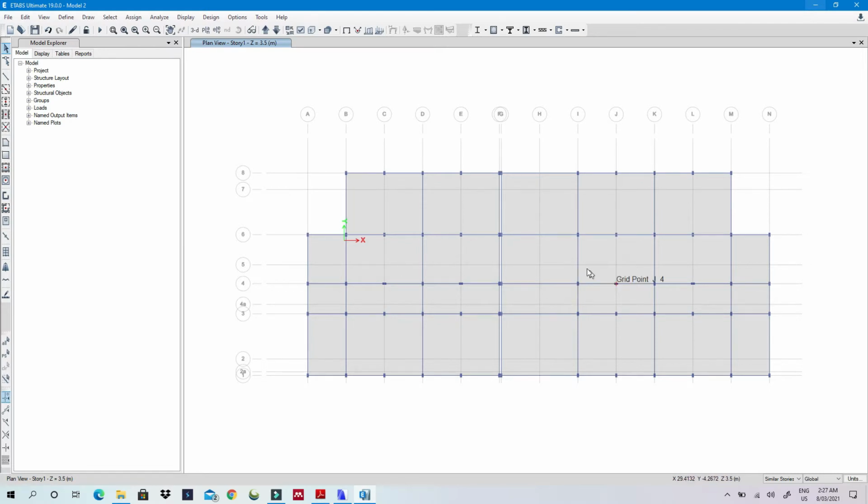Okay, so I said I would explain why I won't be making stairs. If you model a stair here, it will put loads on your beams and columns, and that's the right thing to do. But in the final result, the reinforcement and sections won't have a big difference.